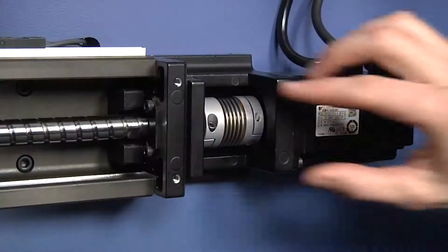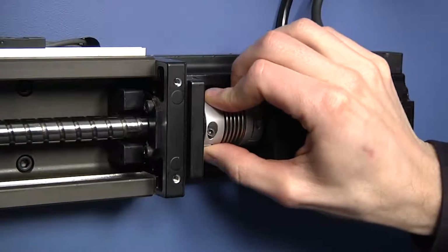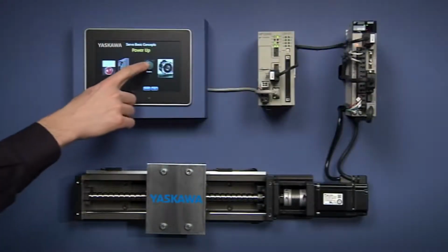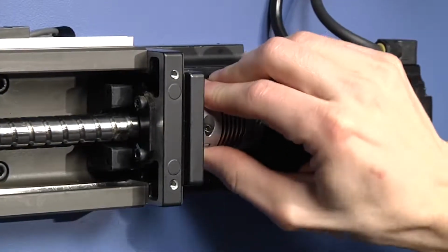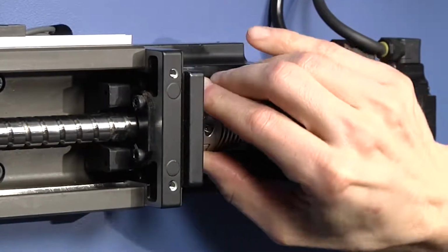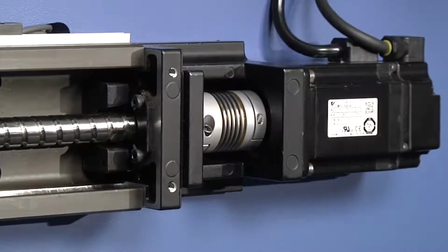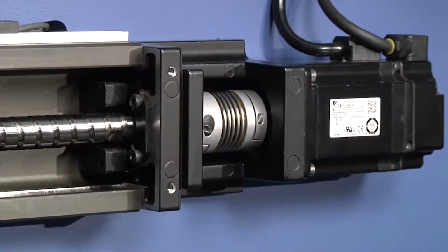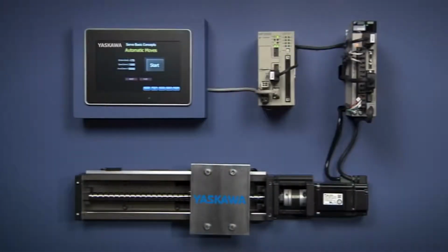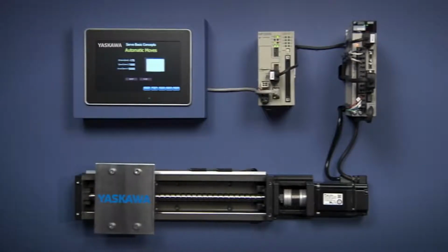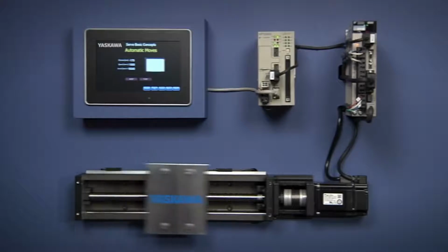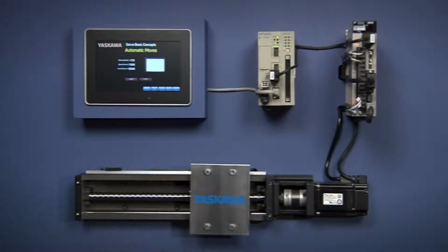Before the servo is enabled, the shaft will easily move. But if you manually try to turn the shaft while the servo is enabled, it will hold its position. You may hear a hissing sound as the servo works to maintain this position. After the servo motor is energized, the controller typically requires the operator to press some type of a start button. At this point, the controller will command motion according to its program.